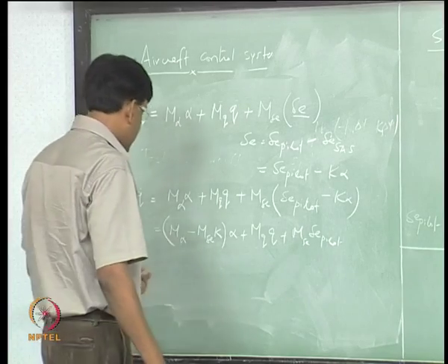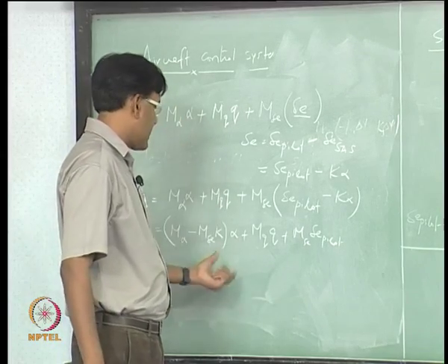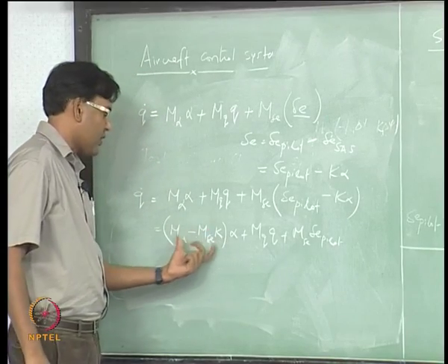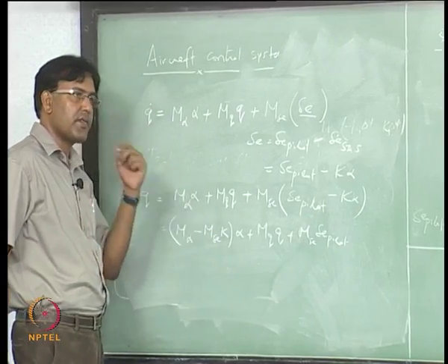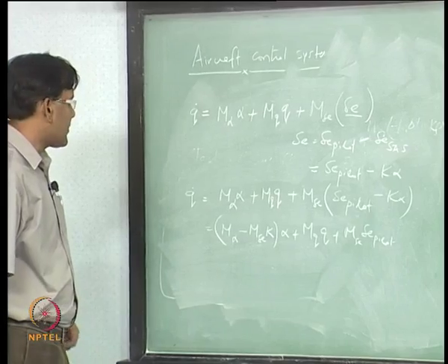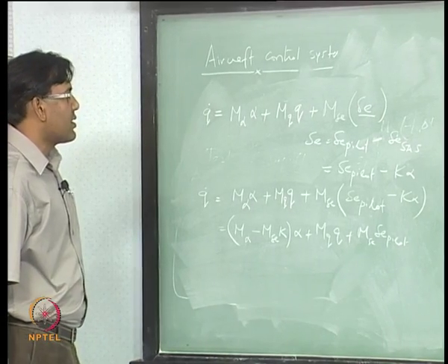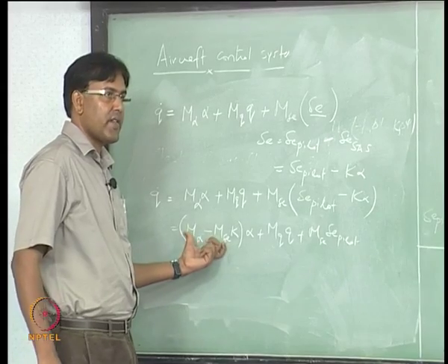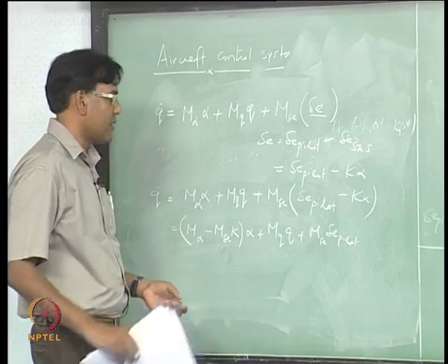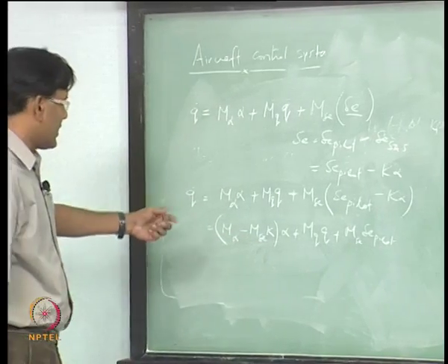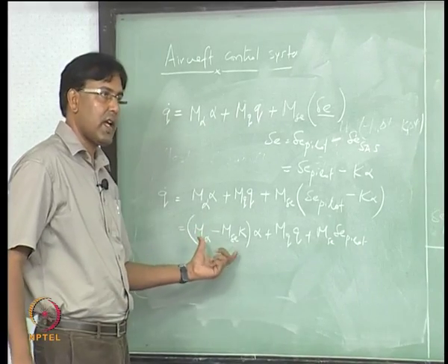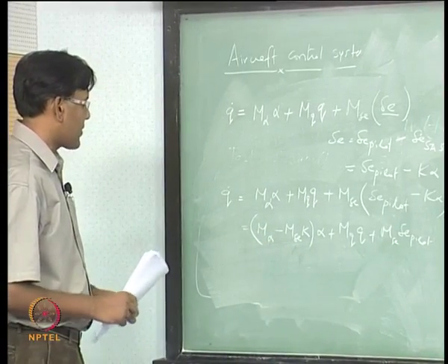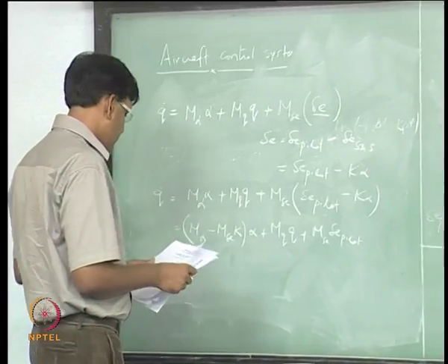So, now because of this stability augmentation system in place, this quantity which is representing the frequency of the short period motion is automatically modified, and therefore, it has an effect upon the dynamic response and the stability characteristic of the aircraft in short period motion.